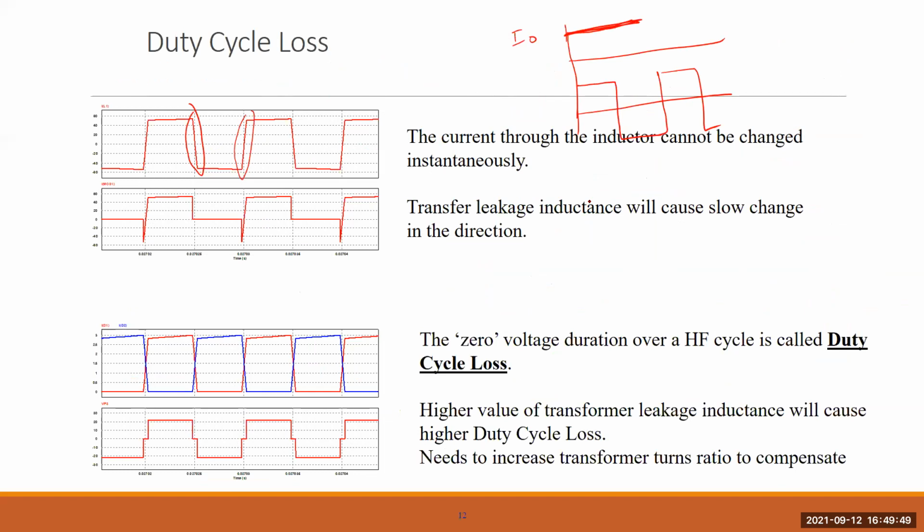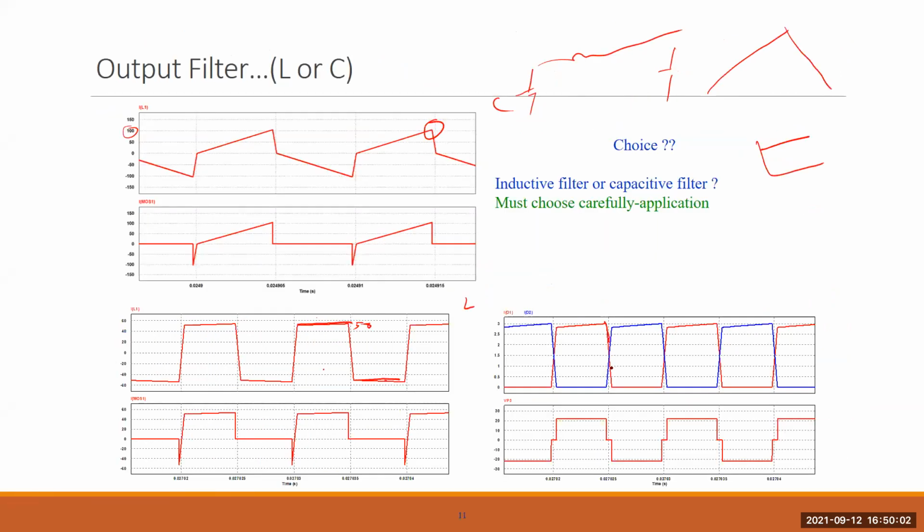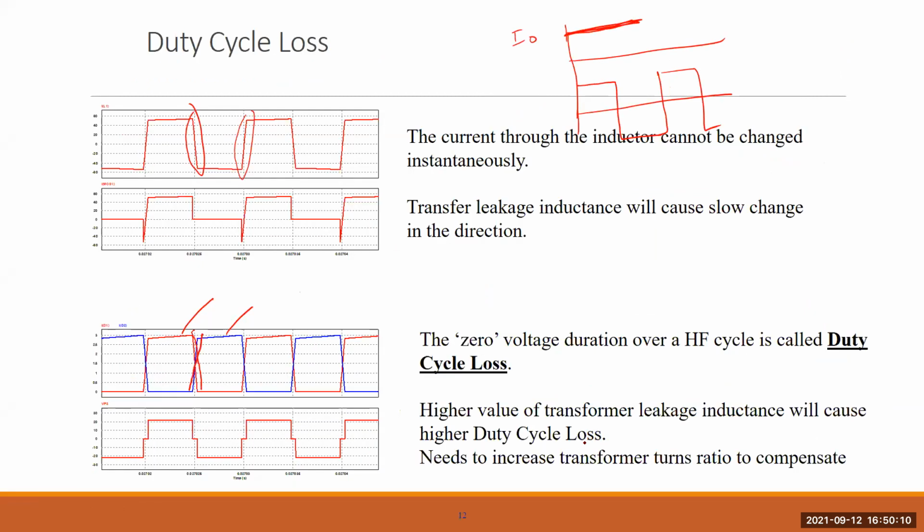That's what you can see, that all four diodes are on. This is say D1 D4 and this is D2 D3. In one pair the current is decreasing and in the other it is increasing, right? All the diodes are on, causing a short circuit across the secondary.